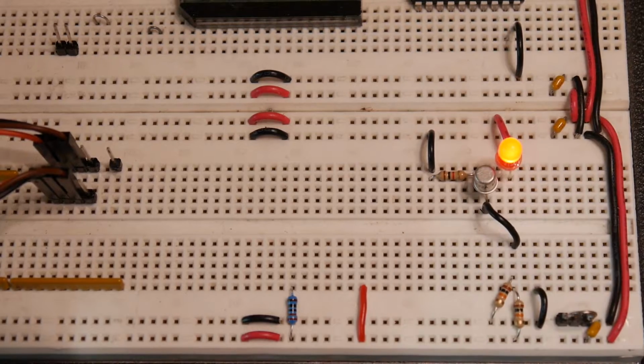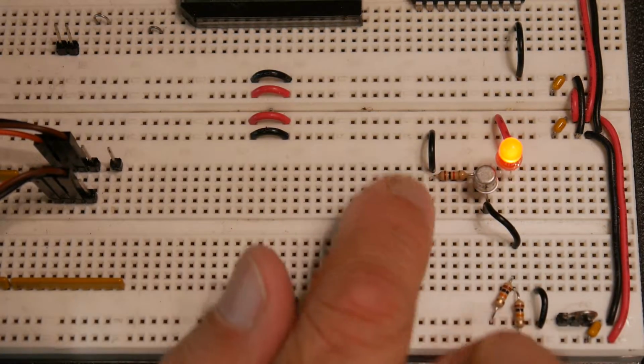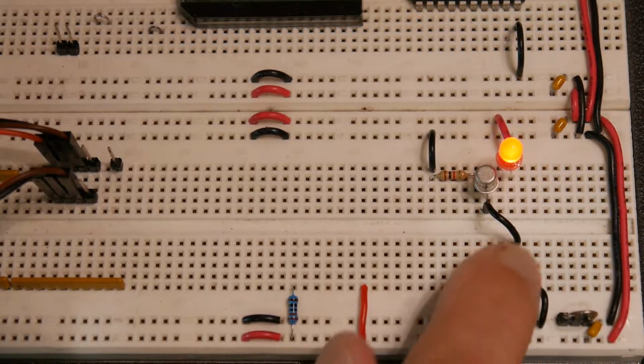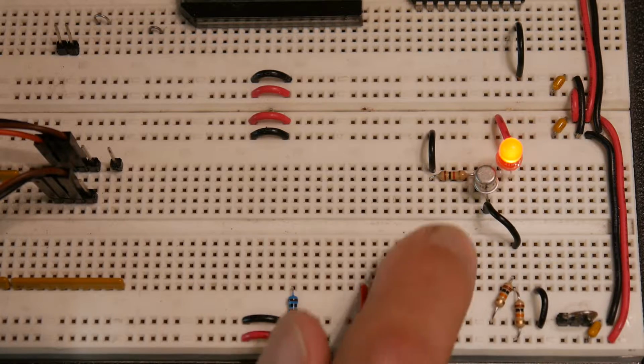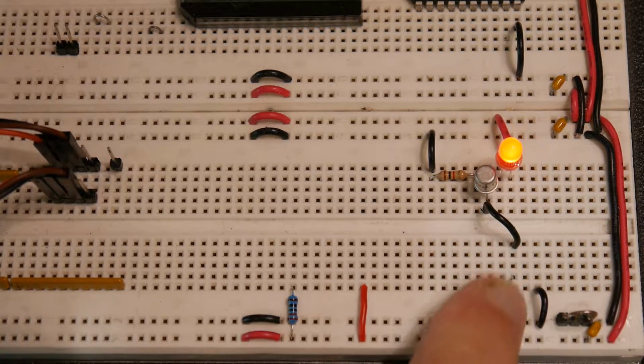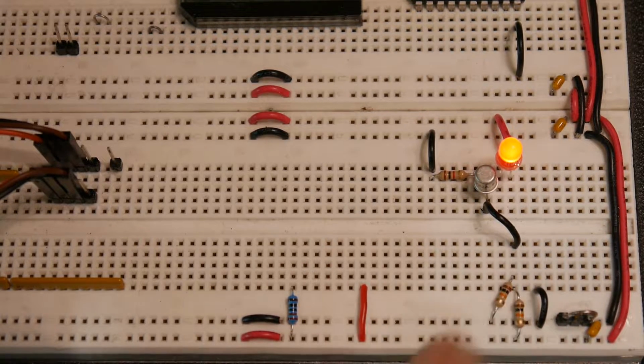We've created a current source with one transistor. Now that current source is going to vary with the VCC because the voltage will go up and down, which means the beta, the half of that will go up and down, and the base voltage will go up and down, and then the voltage across that resistor will go up and down. So we want something a little more stable. Okay. Instead of using two transistors, we could do what we've seen before on our amplifiers where we use a diode. So let's take a look at that.